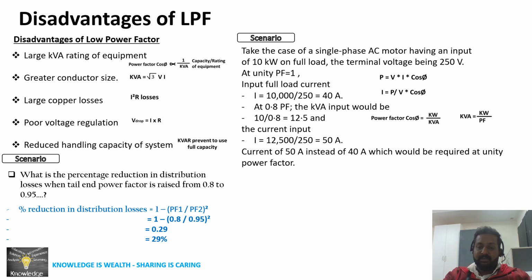So that is why it is very important to maintain our power factor at a desired level. Not unity power factor always. Okay, the optimum power factor which the building needs, based on the building load. We need to calculate the desired power factor and maintain it. If the desired power factor is very low, then obviously you may plan to surrender some contract demand if you don't have any future plan of expanding or adding additional load to the building.